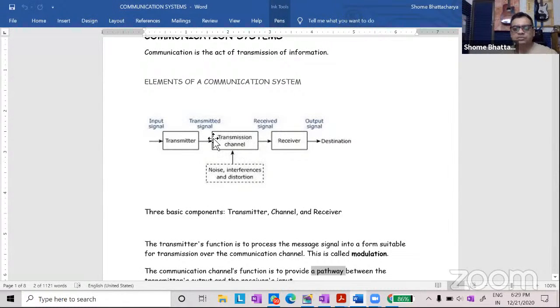We'll understand what this mixing means; the term we use is modulation. It uses that input signal to modulate something called a carrier wave. A carrier wave is a high frequency electromagnetic wave, and that modulated carrier wave becomes our transmission signal. That is what the radio station's antenna is now going to transmit.